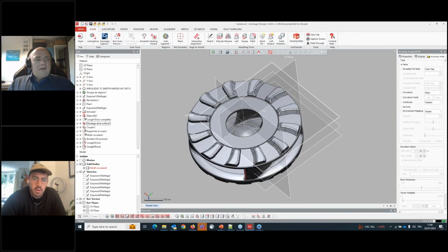Yeah, I think this is regarding the surface I build with the mesh fit. Yes, you can make lines or by section and make a loft afterwards instead of doing a mesh fit. Or you can also make a loft directly with the loft wizard, which is going to be a fully parametric loft.